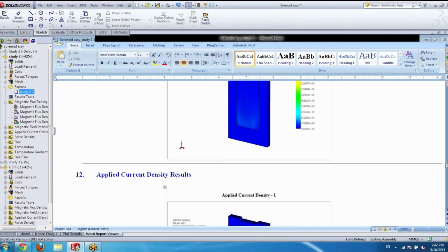I've helped a lot of clients with that, and I haven't had that issue, because if you can manage to get the original one to mesh, because basically mesh will fail because there is a disproportion between certain parts, like very huge parts and very small parts, and that disproportion kind of creates an imbalance. But if you can manage to actually mesh the original configuration, then you don't have that issue anymore.